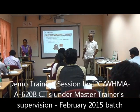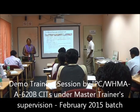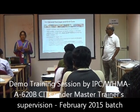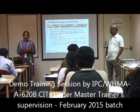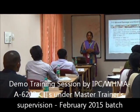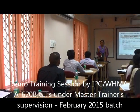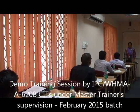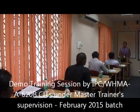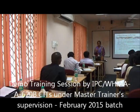Continue. The next point is strand damage or end cuts. Can you people tell me where are the possibilities? What are the possibilities you make while stripping? You damage the conductors. Selection of strippers, then selection of settings. Okay. There are many ways you can damage the strands. So what are the acceptability criteria when you come across such strand damage while stripping the insulation?